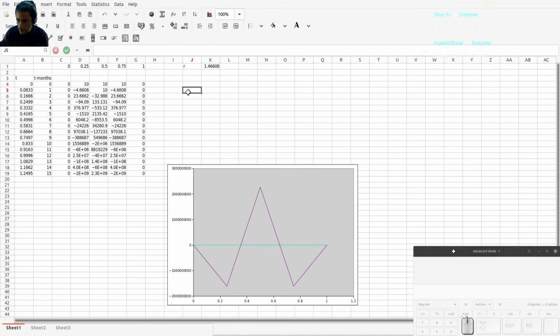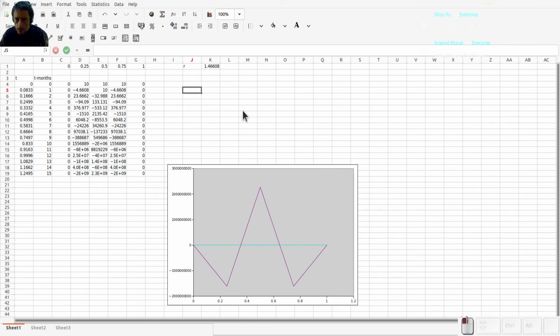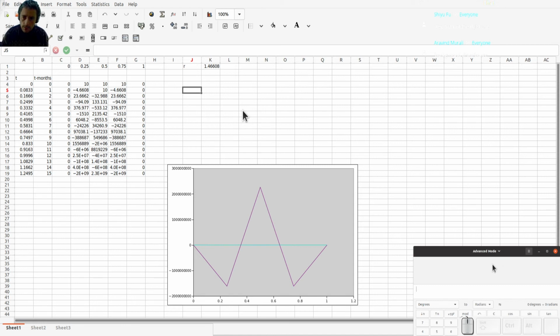So I wanted to have, where's my calculator? Okay. So we wanted to have CV equal to delta t equal to c delta z squared, so 0.25 squared divided by 2 times 1.1, oh, 0.024.